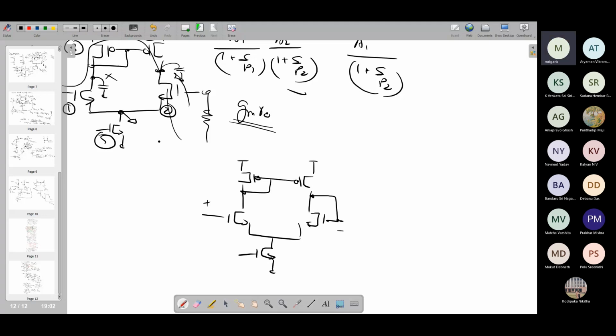So again, in this voltage follower, you need to make sure about the voltage range you're applying over here and the following voltage over here. The range will be determined by the saturation region condition for the transistors. So there will be only a certain range of input voltage for which it will reliably act like a voltage follower. And since the open loop gain is relatively low, you have only one stage, so it will be less accurate. You may have significant error between the input and output voltage. And if your gain is higher, then it will become closer and closer.